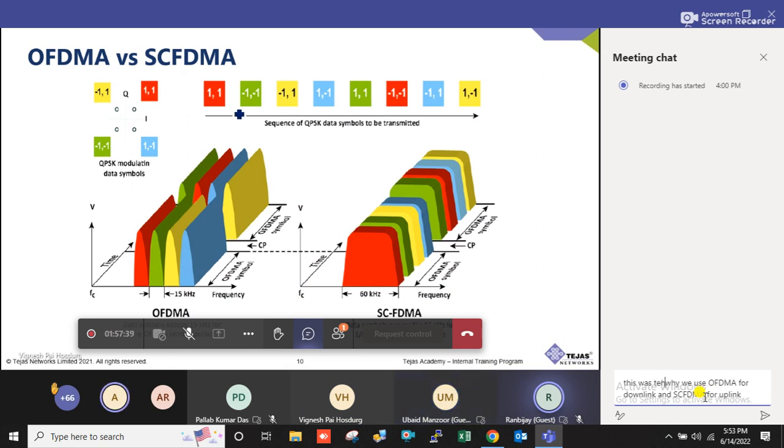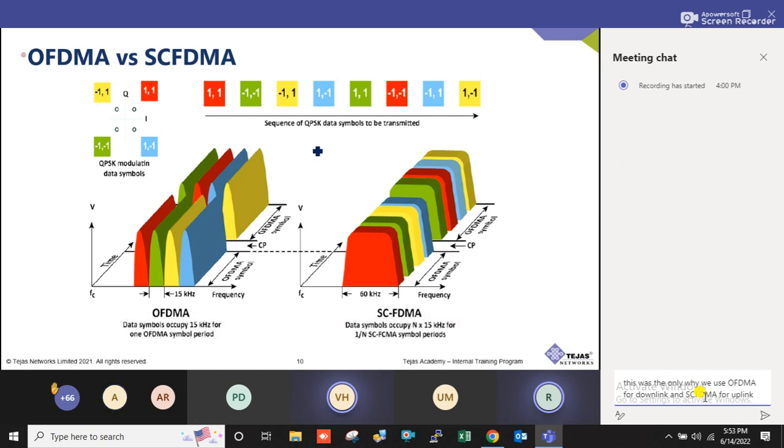Okay, see, basically, if you look at it characteristics wise, both are doing frequency division only. The RSSI or these things have an impact, but it's also about the PAPR issue. That means this one has a higher PAPR, whereas this has a low PAPR. The peak to average power ratio will be less. That means this is more power efficient when compared to what we have in OFDM. That means this requires more power to send and this requires less power to send.